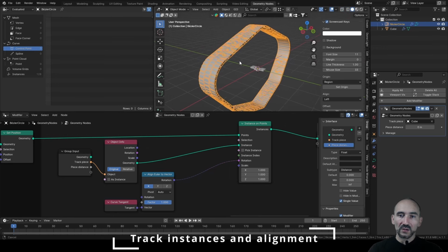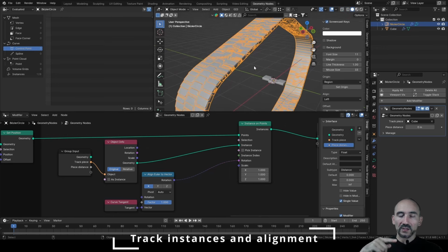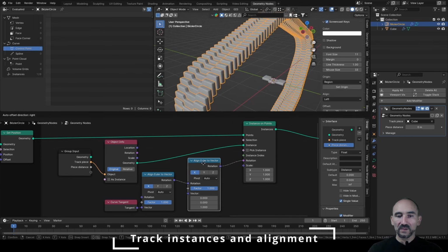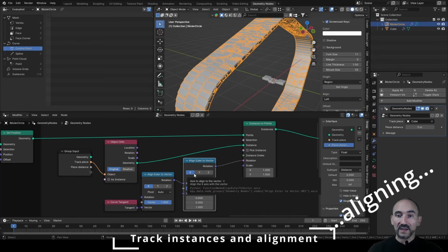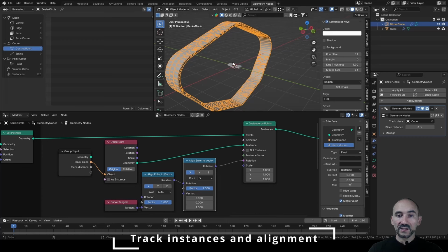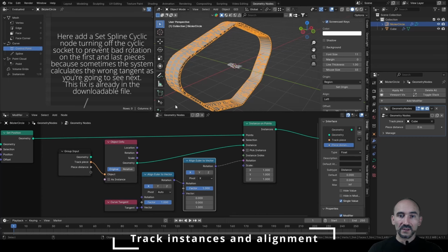But keep in mind, because we can have a correct rotation along the path, but a tilting if something's wrong in the making of the automatic curve from the system, we need to duplicate this another time, saying to the system that we want to maintain the pivot point on the x, so we want to maintain the previous axis we used to align the rotation to the tangent, and maintaining the y-axis of the original object on the y-axis of our curve system.